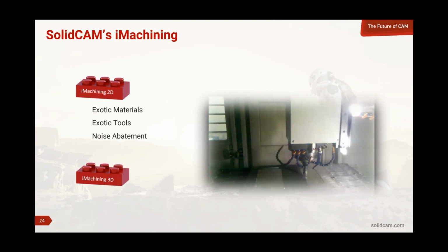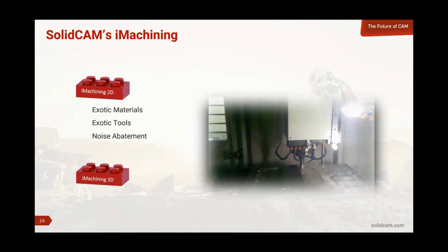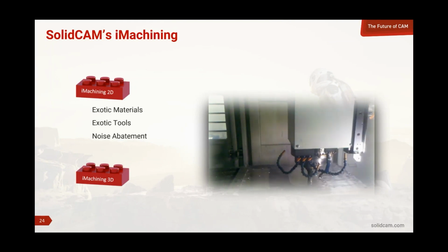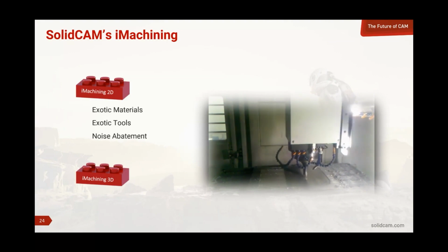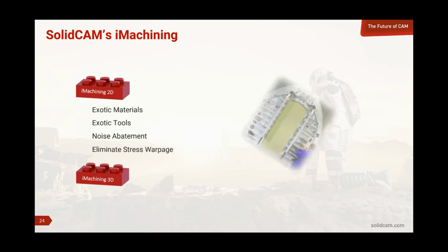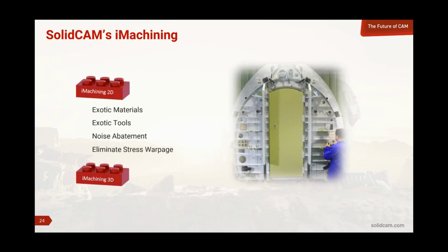In this particular case, I'm running twice the depth of cut that they recommend, but I'm using an iMachining methodology. I'm only running at 50 degrees cutting angle. I'm running at 4,300 RPM and almost 600 inches a minute, about 550 inches a minute. The normal way, the spindle load meter was over 90%. In running this, the maximum it went to is 57%. So again, very, very powerful control over the tool and changing the game, even working with inserted cutters.